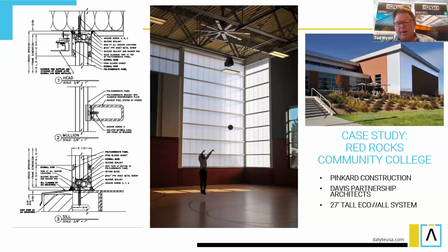You just work left to right. And again, we just need interior purlins about every 8 to 10 feet horizontally. On this job, the architect actually added more purlins than required, and those were to line up with some of the surrounding storefront and window systems.